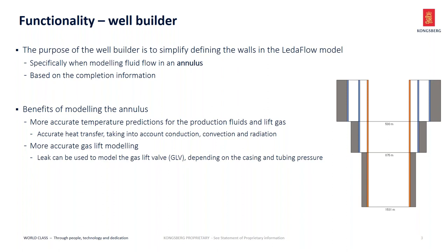The benefits of modeling the annulus in the LedaFlow model are to get a more accurate temperature prediction in the well, both for the production fluids and the lift gas. So obviously there is heat transfer between the lift gas in the A annulus and the production fluids, but also if there's lift gas in the annulus, then there can be radiation heat transfer between the tubing and the casing, and all of those effects are taken into account when you model the annulus in LedaFlow.